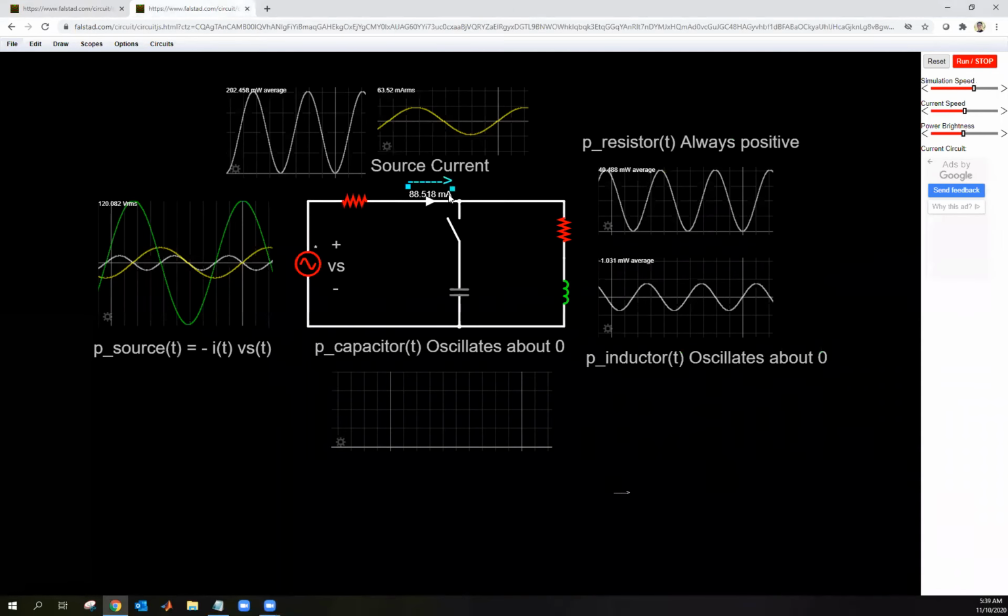So let's look at this next one. Okay, what do we got going on? Look at this. I have a voltage supply. I have a resistor. I have another resistor and an inductor. And what I want you to think about this system as, you've got PG&E, our utility company, and you've got the transmission line losses, or the resistance in the line. And let's imagine this entire system, these 2 branches on the right here, is your factory, right? Maybe it's your power plant, whatever it is. Okay, so let's say your factory has a lot of motors. So we represent those motors with resistors and inductors, okay?